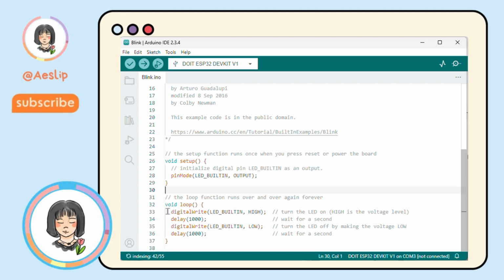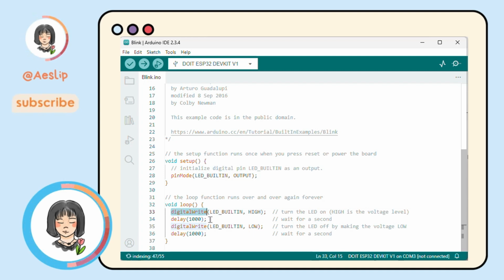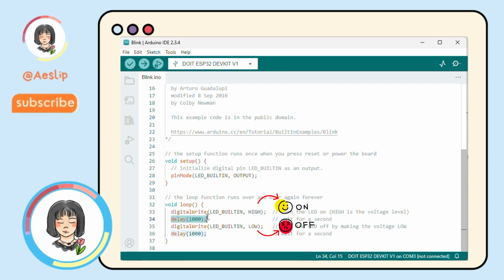After the setup function runs, the Arduino will enter the loop function, which runs continuously in a cycle. This is where the main logic of the program is executed. This line turns the LED on. digitalWrite is a function that sends a high or low signal to the specific pin. By sending a high signal to LED_BUILTIN, we activate the LED.